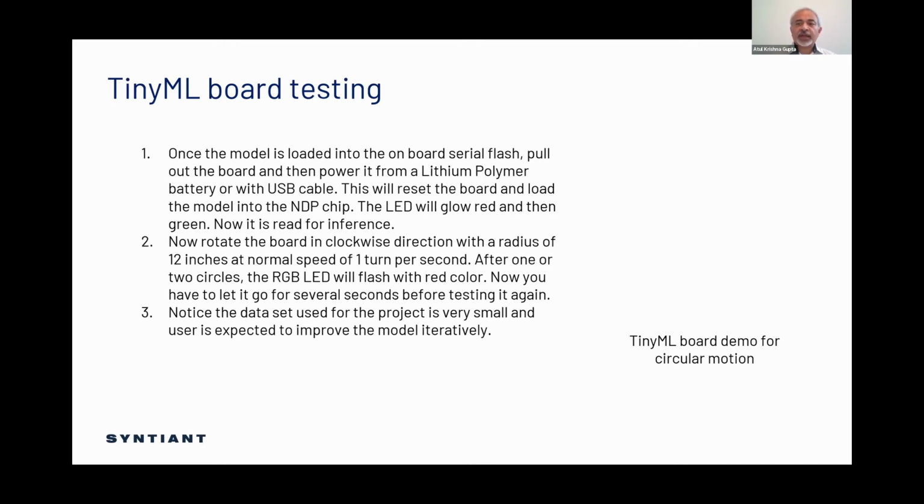If somebody wants to add any other sensor, then it has to be connected through our GPIOs. And then the data first goes into the SAMD21, which is a host processor. And over there, you can actually do some pre-processing if you like, and then make a tensor. And then you can actually send the signal to the SPI. So yes, it is possible that you can actually use any other sensor.